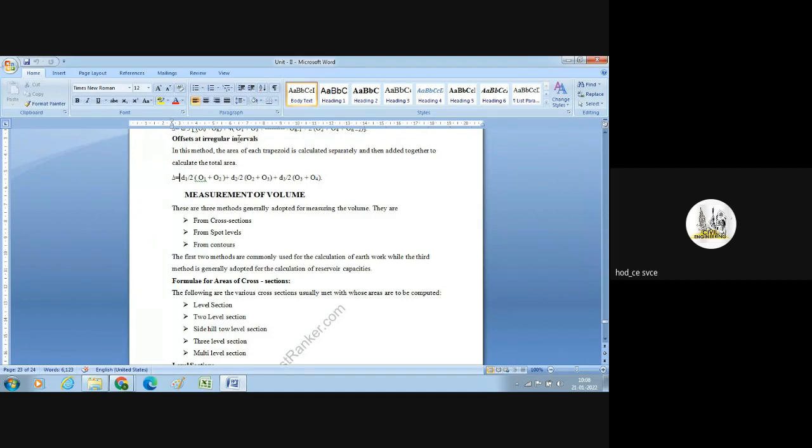What is the distance from the meridian to the B point? The departure distance at the point A is 0 because it started along that point. Next, we take the distance from the meridian to the point B, which we have taken as departure distance D1. After that, we located the midpoint of the line AB, then took half of the departure distance.